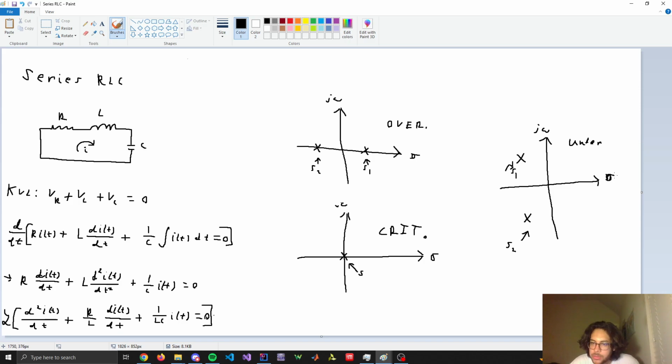So basically, what you realize is that poles that are purely real lead to purely exponential solutions. Just like these two, overdamped and critically damped, they're real numbers, so they're only exponential. But if it's a complex number, see here, this vector would be pointing to sigma minus j omega, like this. So it's a complex number, but its solution in time domain has sinusoidal oscillation. And realize this one has a real part and an imaginary part. That's why we have a decaying exponential and oscillation for underdamped. So that case is really interesting.